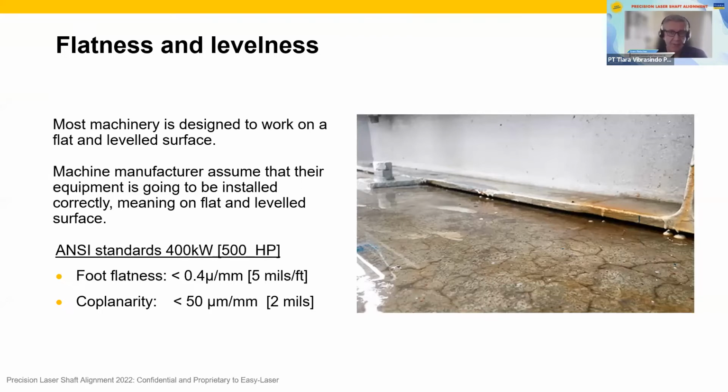So we have here machine or mounting pads, sole plates, frames, and tables. Everything you put on top of those kinds of bases is going to be affected by the condition of the base. When the flatness is out of tolerance, the rotating equipment is affected. You will have a soft foot, there could be a misalignment, machine casing stress, pipe flange misalignment, many other causes. But I want to mention specifically one, and that is the strain on bearings.